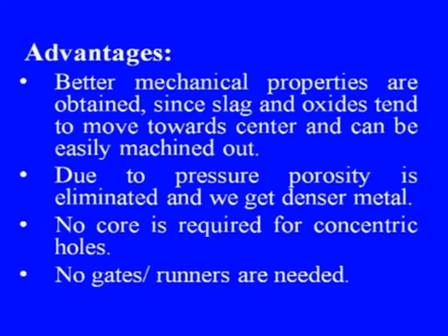Now, let us see the distinct advantages of this process. Better mechanical properties are obtained, since slag and oxides tend to move outwards and can be easily machined out. Due to pressure, porosity is eliminated and a denser material can be produced. No core is required for concentric holes. No gates or runners are needed.